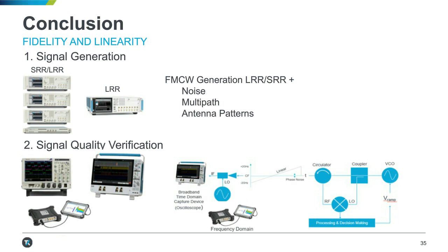If we want higher levels of fidelity, then we would move to a higher sample rate oscilloscope, such as a 70,000 oscilloscope. If we want to do good frequency domain measurements, I recommend that a spectrum analyzer is always the best tool for that. And Tektronix has a range of high dynamic range, high performance real-time spectrum analyzers.